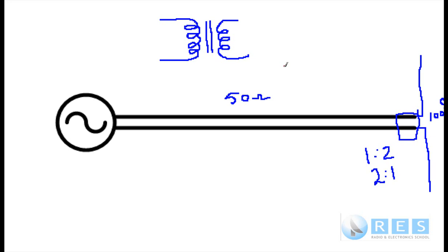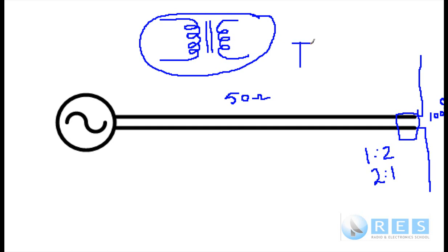There is absolutely nothing in common between transmission line transformers and mutually coupled transformers like we'd use in a power supply. We can use them as baluns, but we don't, because they're too narrow band. They're used by people like radio broadcasters who are transmitting on the same frequency. They would use a transformer type balun like that. But the baluns that we use in amateur radio are called transmission line transformers. They use the principles of transmission lines to work and not the principles of mutually coupled transformers.